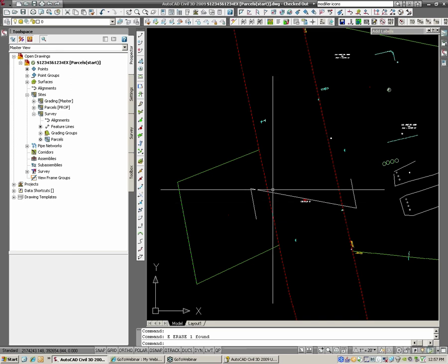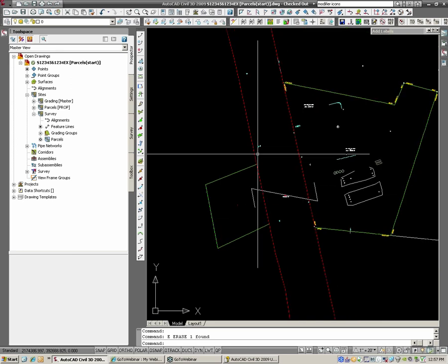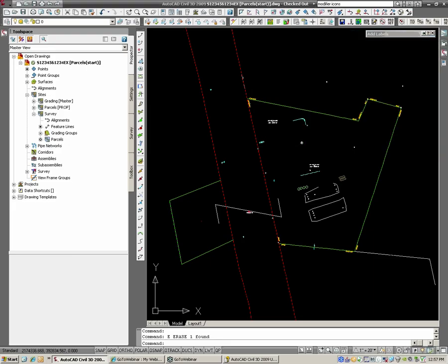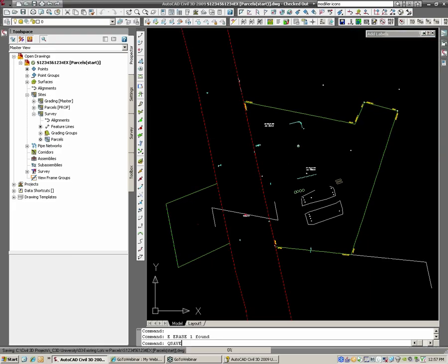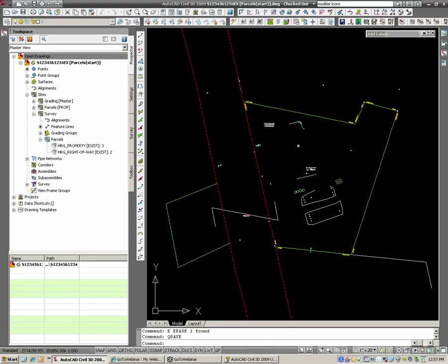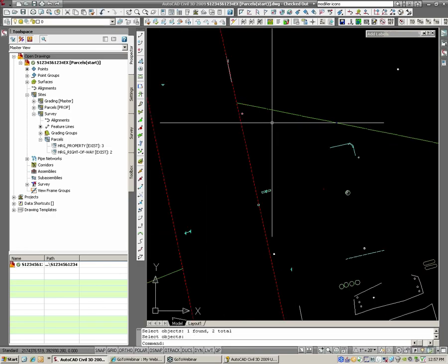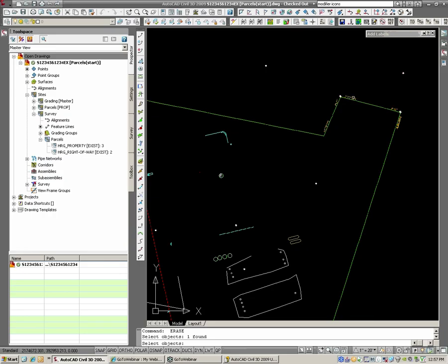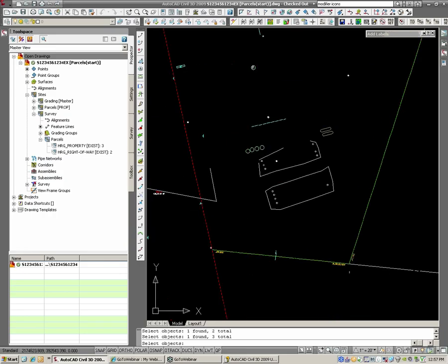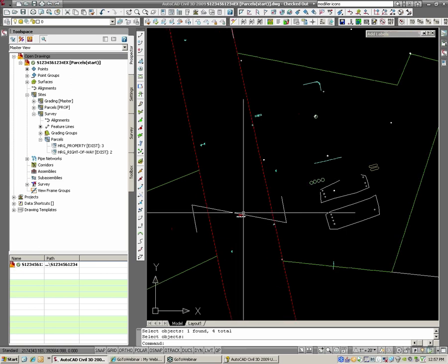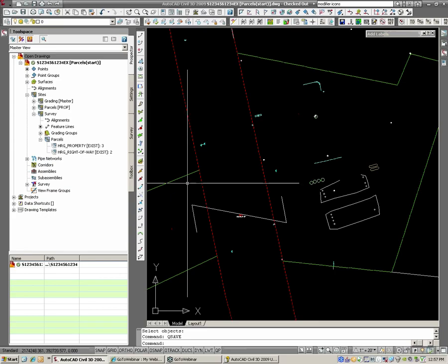One thing I'm going to leave here with is that parcels, anything in Civil 3D, and I can't explain this enough, anything in Civil 3D can be labeled through the XREF. So I'm going to save this drawing here. I'm going to delete these area labels I have. And I think it's more important that we start labeling stuff through the XREF than it was before in Land Desktop. The reason we didn't label through the XREF in Land is because if I update something, I'll have to update so much text. But that ceases to be important with Civil 3D because you're labeling through the XREF, labeling the model itself.